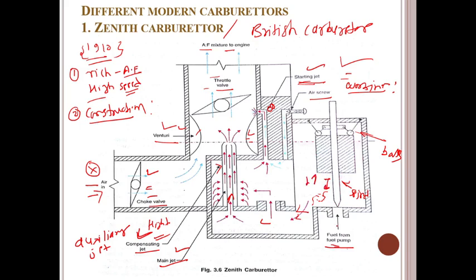When the spindle moves up, the fuel enters inside the fuel chamber. When fuel supply to the fuel chamber decreases, the two floats come down and the two balls also come down with them. As the balls and spindle are connected like a seesaw, the seesaw position is done with the help of these balls, guys. So when the balls come down, the spindle comes up and the fuel passage to the fuel chamber is unblocked.